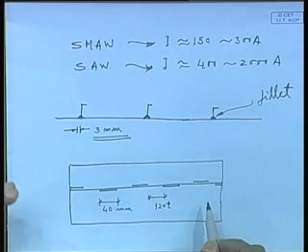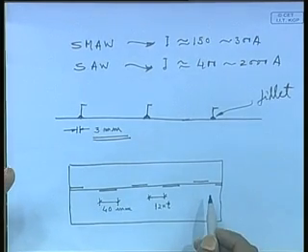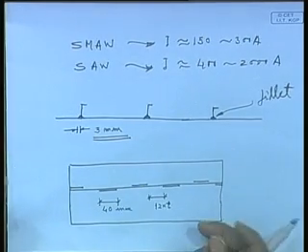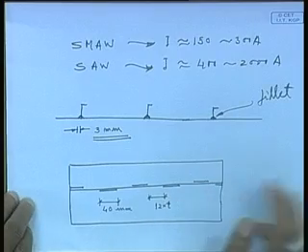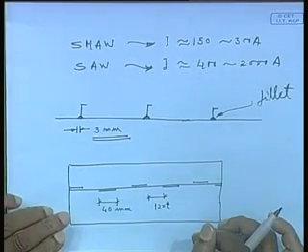So only where it is not a very load bearing structure, for example the partition bulkheads in the accommodation region, in the deck house, the partition walls between the cabins, there one may go for such staggered intermittent welding, but still, from another point of view, it is not very preferable.